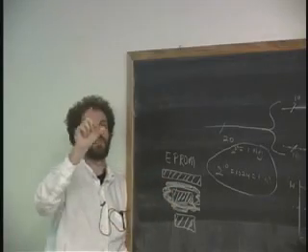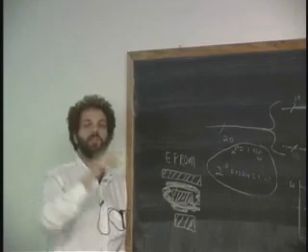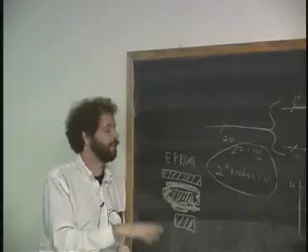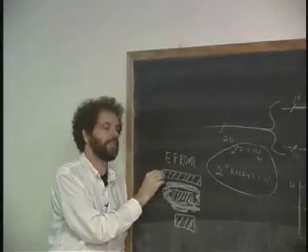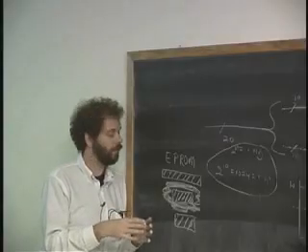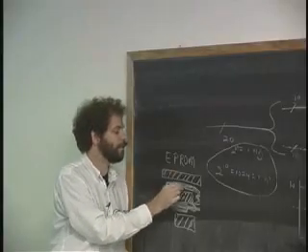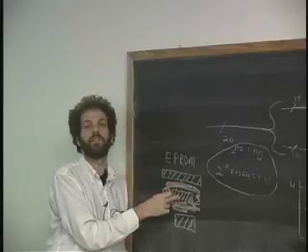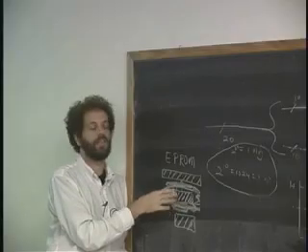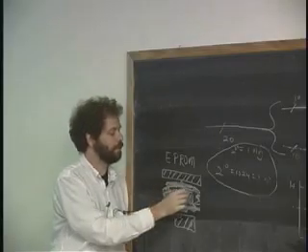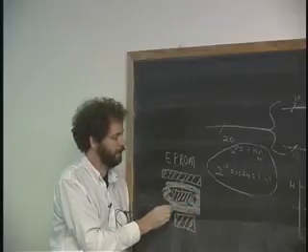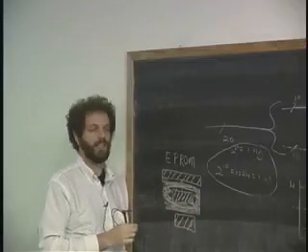And ordinarily, when you walk around with a chip like that, you don't have 20 volts to get to the other side. So the chip will last for 20 years if you don't put high voltage on it. But if you put this EEPROM inside of an EEPROM programmer, which has 20 volts on it, it can still read or write, store or take away charge from this guy in the middle. And as soon as you take away the 20 volts, it lasts forever. Okay? The guy who thought of this was a wonderful guy. I think he was at Bell Labs. And no one believed him that he could do it. And he actually could.